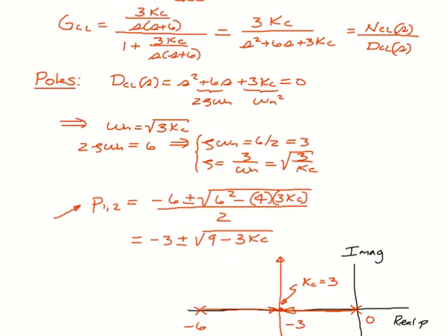if we look back at our characteristic equation, let me maybe write that down in a different way. We know that in our standard form this becomes minus zeta omega n plus or minus omega n times the square root of zeta squared minus 1. Where they hit is when zeta is 1. So when zeta is less than 1, the roots become complex.